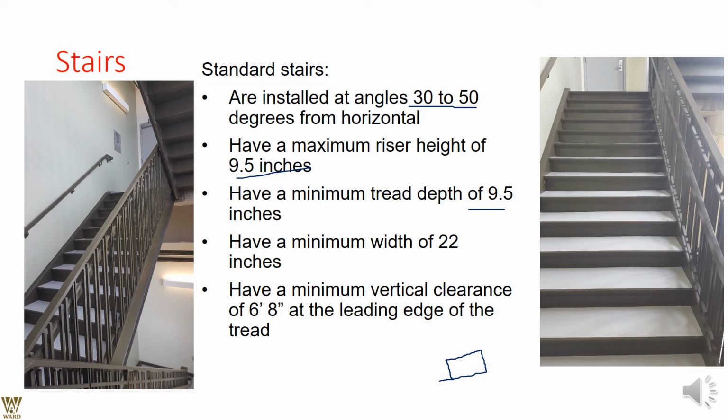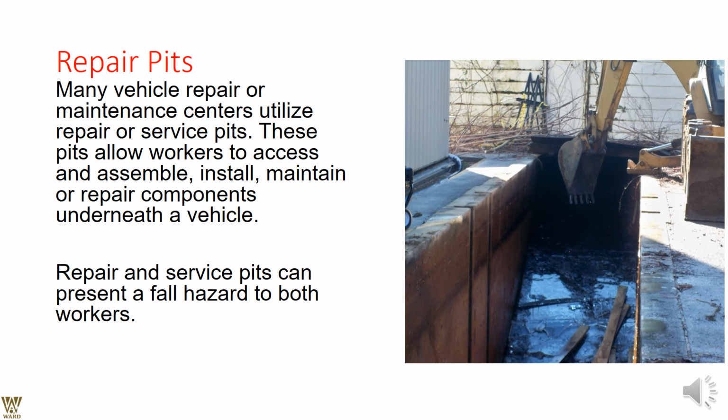I've been talking about the heights. Now this becomes the height and this becomes the breadth. So the length can vary, with a minimum width of 22 inches depending upon the traffic that you're looking into, and the vertical clearance thereby. Always ensure a handrail on the staircase.